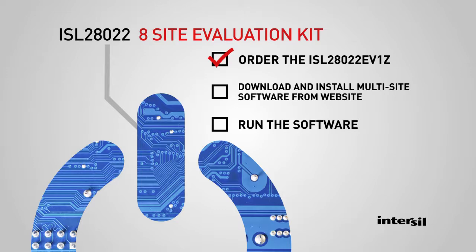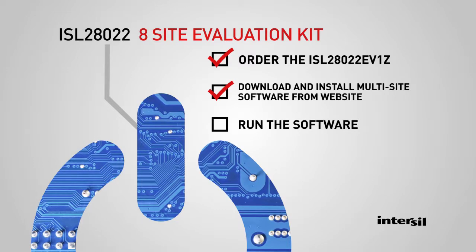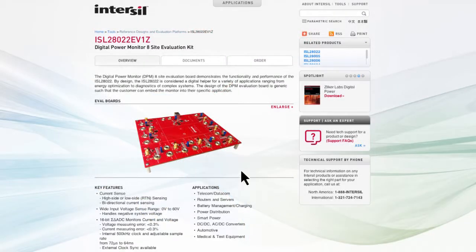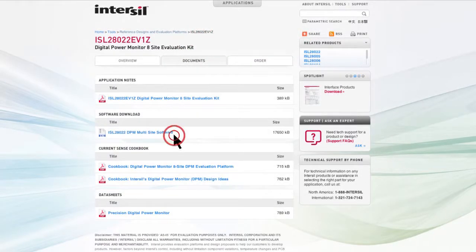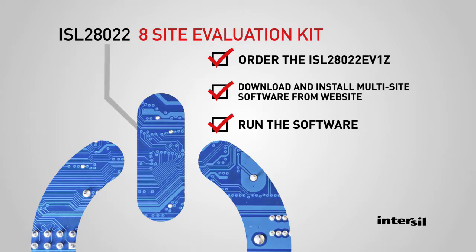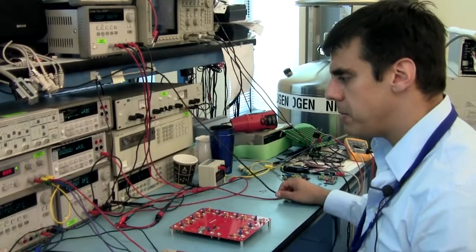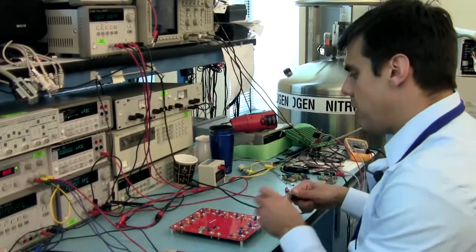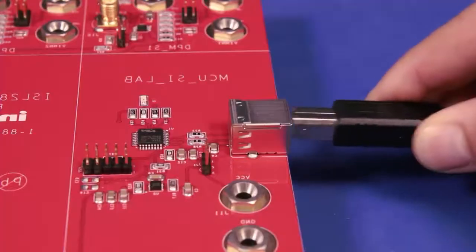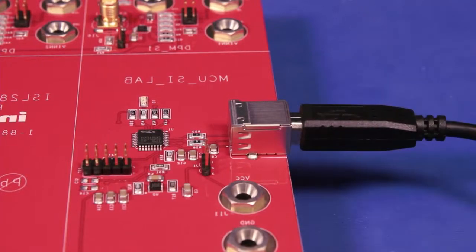Now it's time to download the software. You navigate to Intersil's website and to the ISL28022 eval board software. Choose Documents and download the software under the ISL28022 DPM Multi-Site Software tab. Run the software. Next, you're given a USB cable. You will take the USB cable and plug the cable into the ISL board.